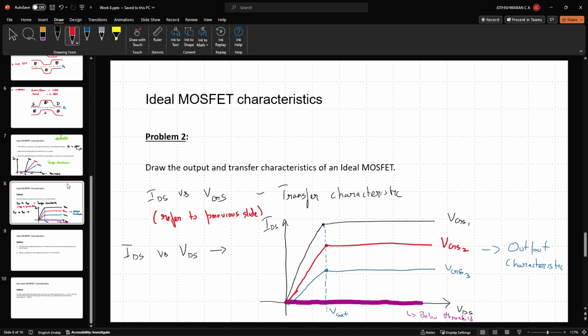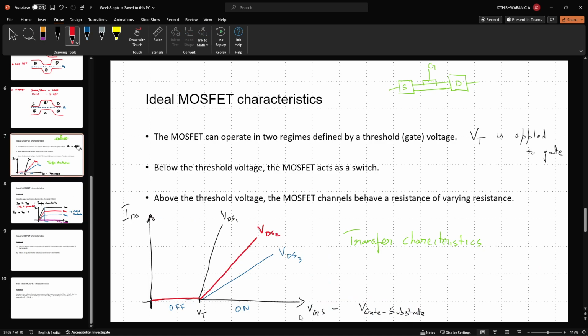And the switching behavior we essentially see from this. If a VDS has been applied, no current will flow if VGS is kept below the threshold. The moment VGS changes above the threshold, the device will switch on. So I shouldn't say below the threshold here. What should be understood here is that switching implies moving from above to below, so it implies this is happening.